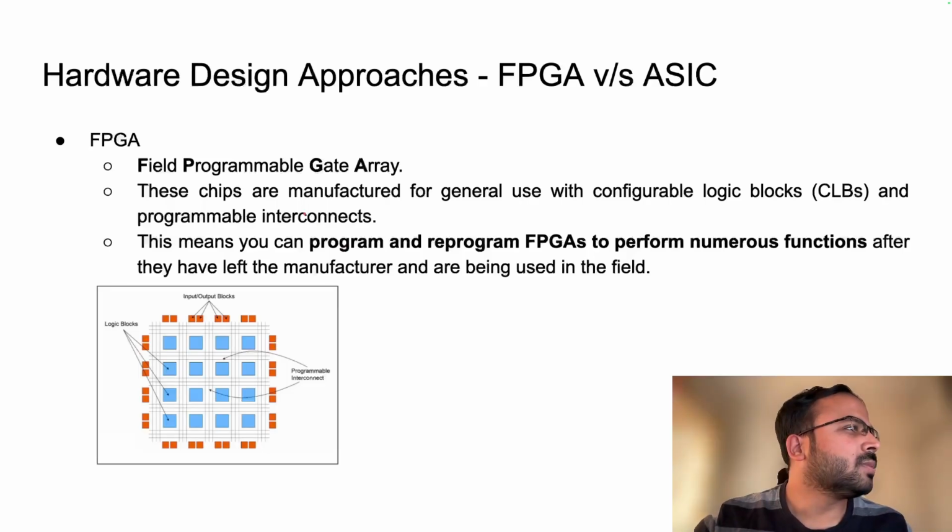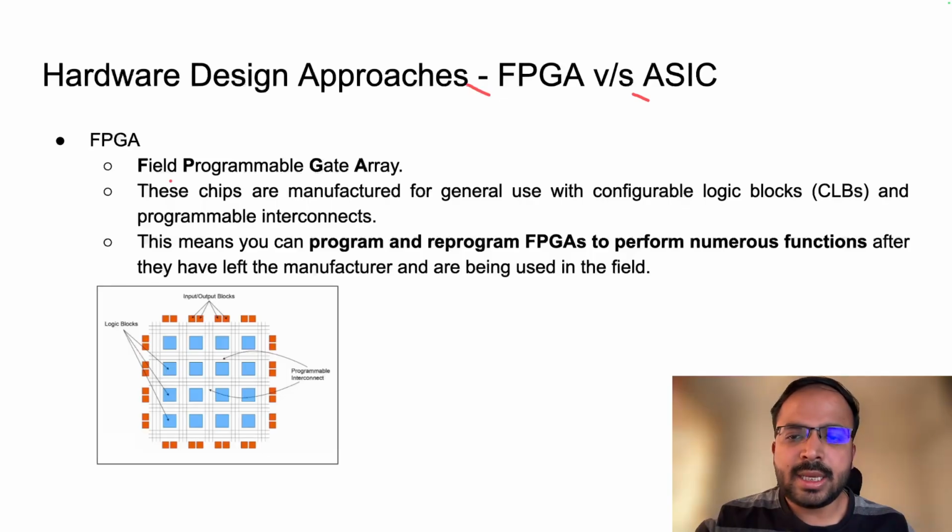So embedded systems in general are designed using two approaches. One is the FPGA approach and the other is the ASIC approach. So what is FPGA? FPGA is field programmable gate array. As the name suggests, this design approach is programmable. You can program and reprogram it, and it is used for general use. It will not be designed only for one specific set of functions.